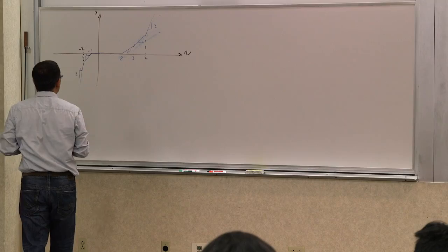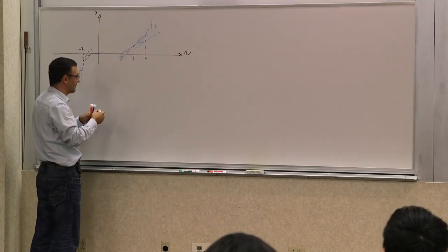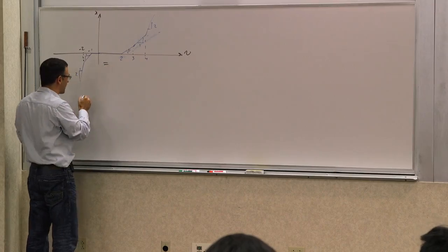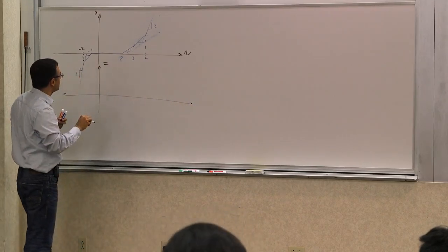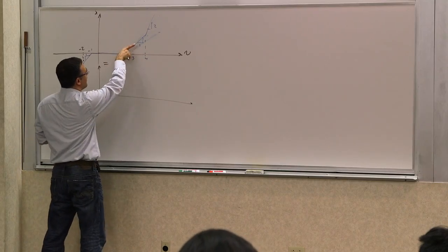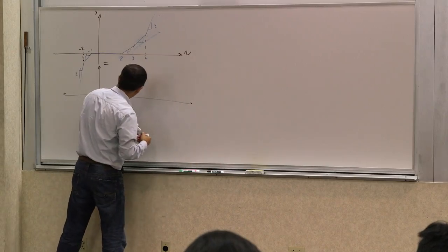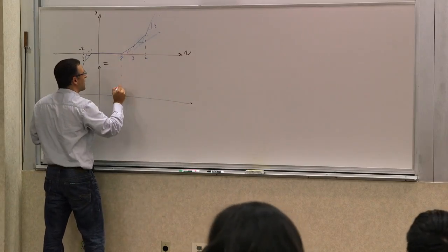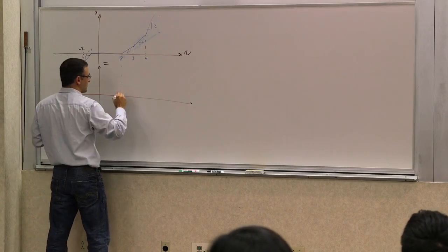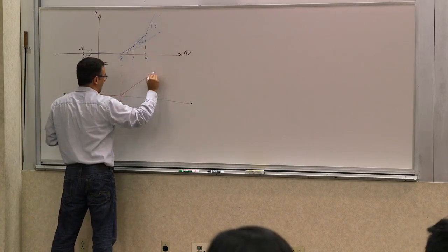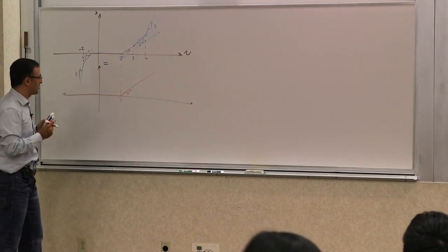How do we do that? So we need to write it as a sum of a bunch of things. One way to think about it is a graphical way. So think about this as this is equal to the sum of a bunch of stuff. So where do I start? Let's say I start with this piece, right? Let's start with that, and I'll have you tell me what the rest of them are. So the first component is going to be something that starts at 2 volts, is 0 all the way, and its slope is 1/2. So this is the first one.